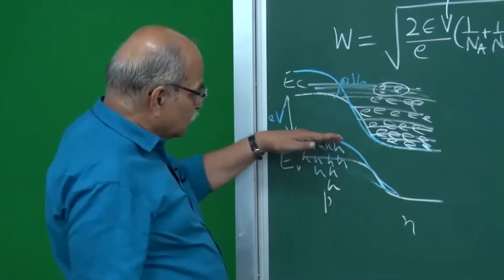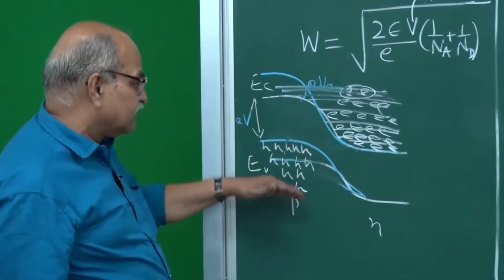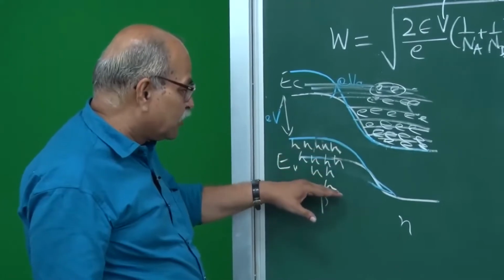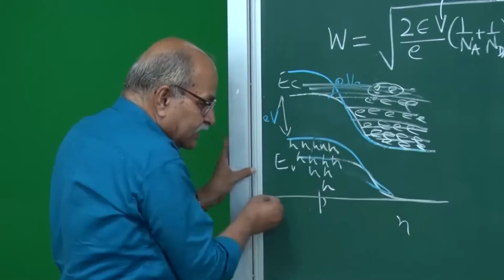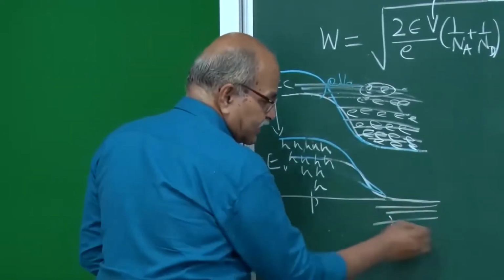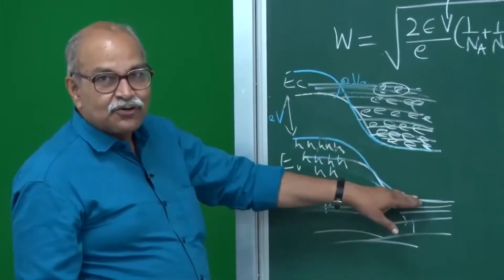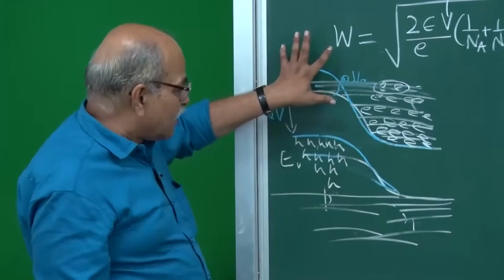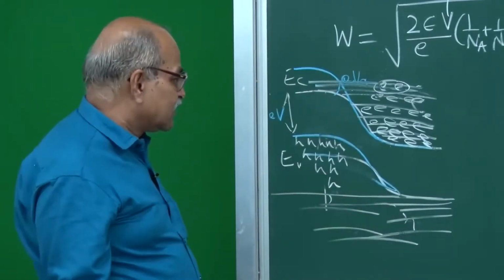As you go away from this point, you have smaller and smaller population, and you have lifted everything up, and anything above this line is not allowed to go here. Your valence band states are here, so anything above this is not allowed to go here, and then you are lifting it up, so that diffusion of holes also decreases naturally.